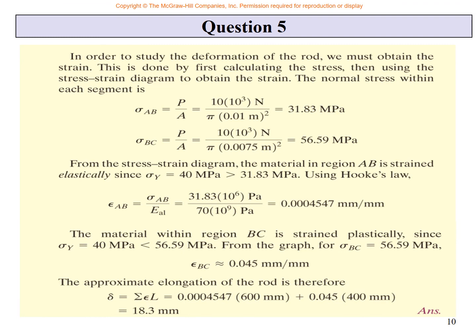So this is important. Therefore, in part AB, sigma is equal to E epsilon, so epsilon is equal to sigma upon E. Sigma is this which we found. E is given in the problem as 70 gigapascal. Remember that all units should be correct. Mega is 10 raised to 6, giga is 10 raised to 9. So you find this is the strain. This is only the strain, not the change in length.